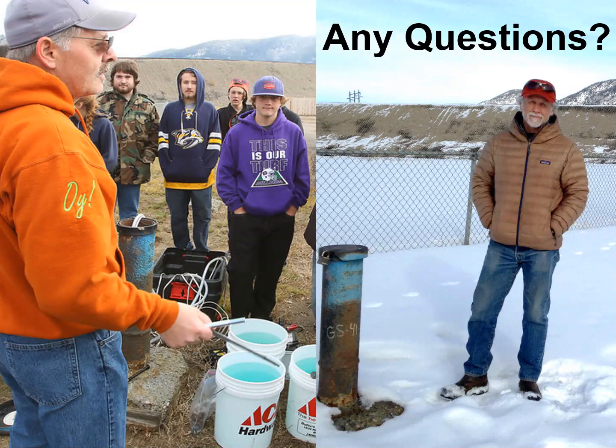So can you sort of explain the difference between total recoverable copper and, say, total dissolved copper? Sure, I can. To start out with your question, Doug, in groundwater, we just measure it as dissolved because we're assuming it is just dissolved moving through an aquifer. It's got to move through small spaces. And in stream, the current water quality standard is the state's total recoverable standard. It is a measure, it is an unfiltered sample.